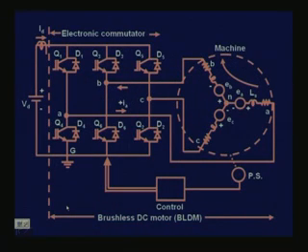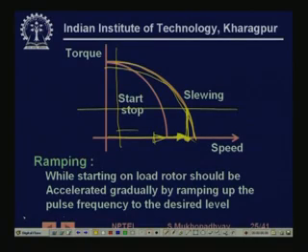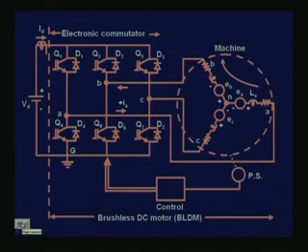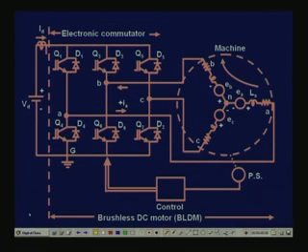That is the basic idea. Without going into too much detail, we will see that these are the three stator phases, and they are excited by what is known as the inverter. Sometimes current is flowing through this, sometimes current is flowing through this, sometimes through this, depending on which inverter legs you are keeping on.